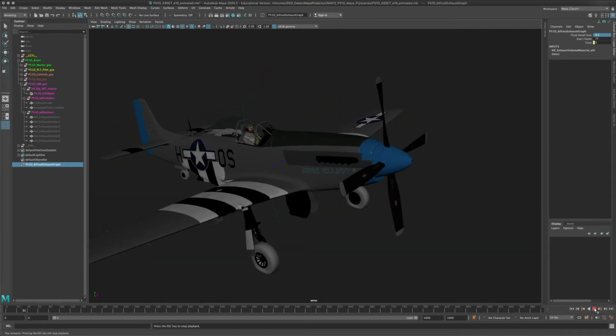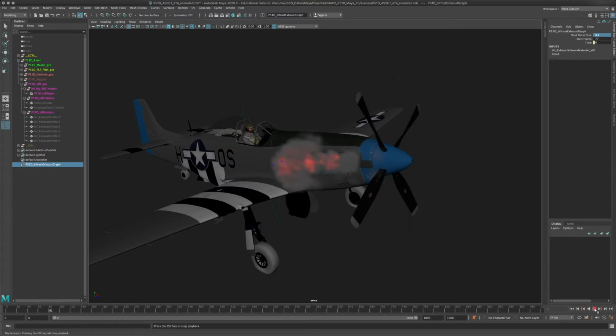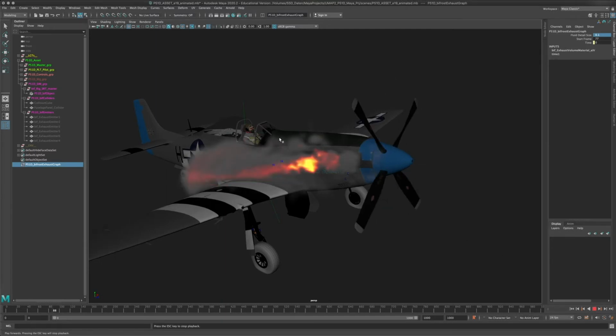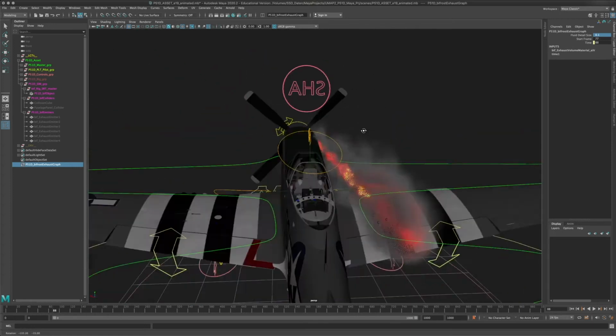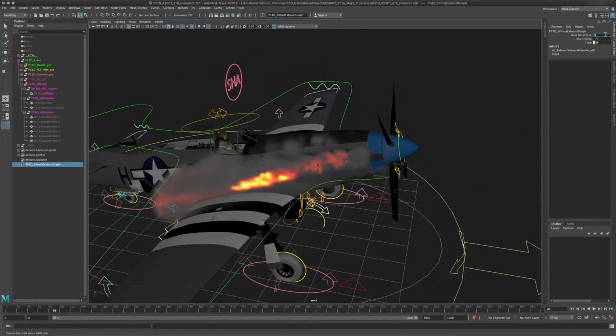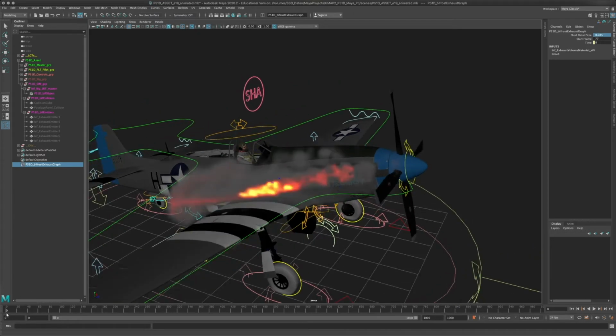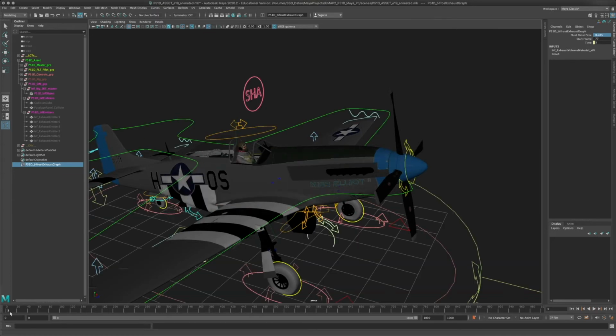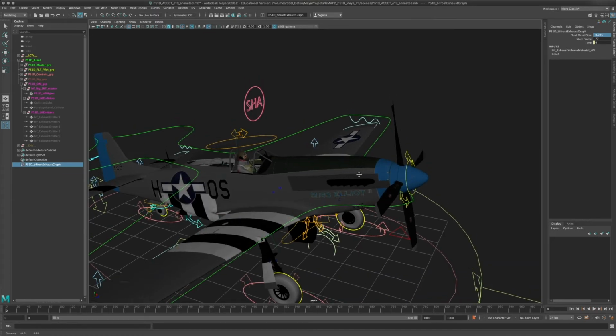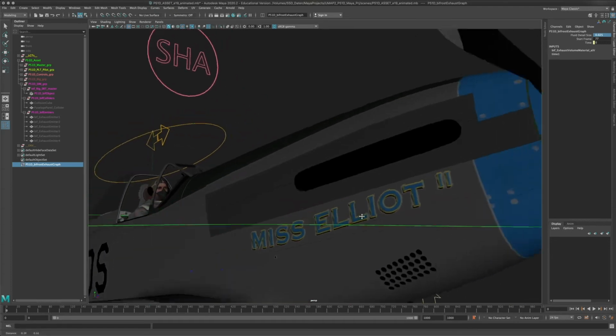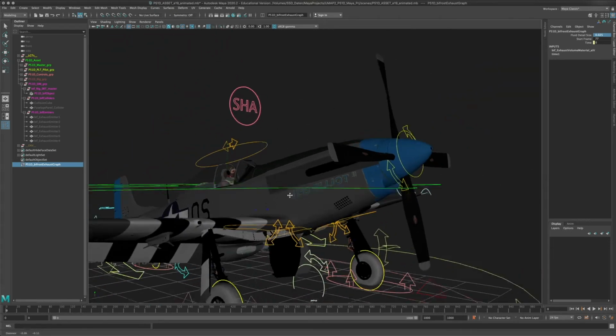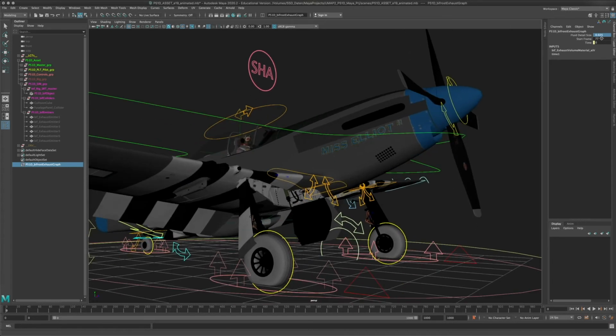If I make the detail size larger, it's going to look pretty bad, but the sim is going to run really fast, but of course that's just ridiculous. So 0.025 is what I've settled on, and there's really not much more detail for it to generate with a higher resolution. You would probably do that if you were this close, but then again you would change a few things about the simulation anyway.